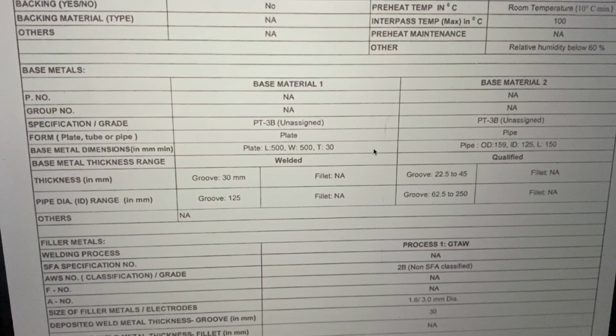P number is a classification of materials, and within the P number, the arrangement is such that we have P numbers arranged based on the welding and metallurgical characteristics of that particular alloy. So carbon steel with different percentages of carbon, with no alloying element, or with minor or major alloying elements, or a different material like stainless steel, which has deliberate additions of nickel and chromium and has completely different